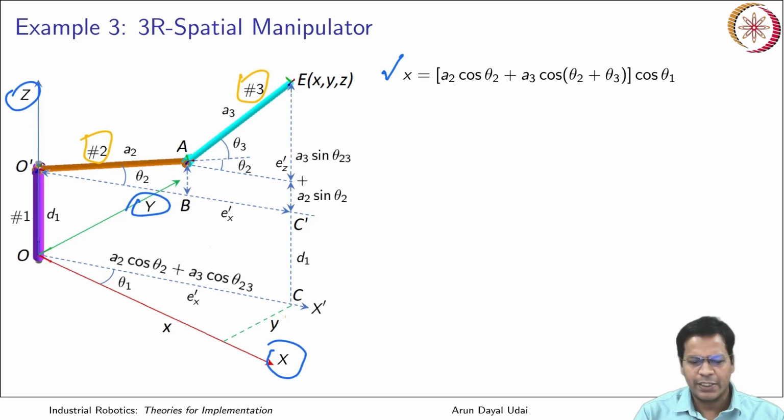That is completely contained in a plane, and the plane rotates about this vertical Z axis. The whole of this rotates. Got it? That is theta 1, which is making it move, and this is your plane. So now let us analyze what could be the components of the 2R subset along different axes.